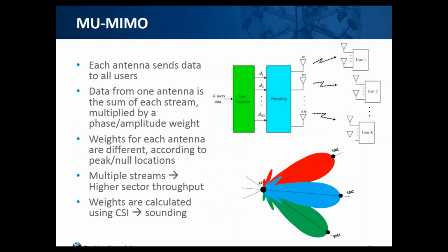So to summarize what we've seen so far, we talked about SISO, SIMO, MISO, and MIMO systems. All these systems have in common the fact that the communication is between one access point and one device. If the access point or the device or both have multiple antennas, we can either receive a stronger signal or send more data, but the destination of the transmission is always one single device. We have talked about transmitting a dual stream or two streams. The two streams are really two parts of the same transmission, and they have the same destination.